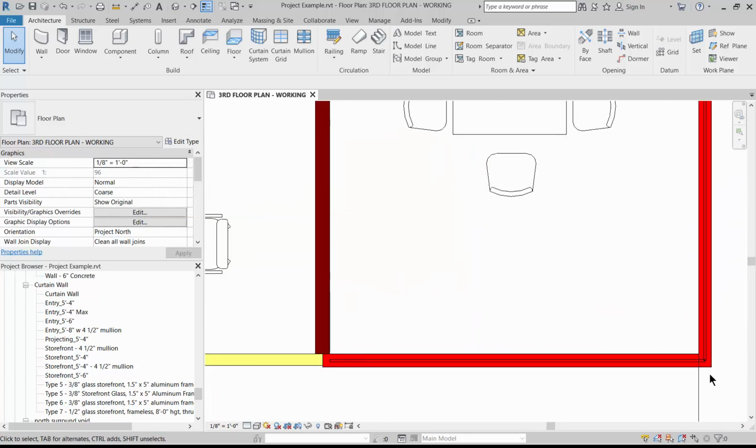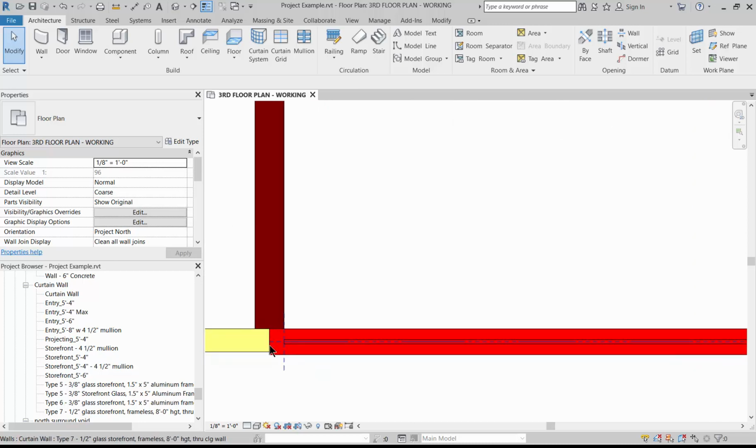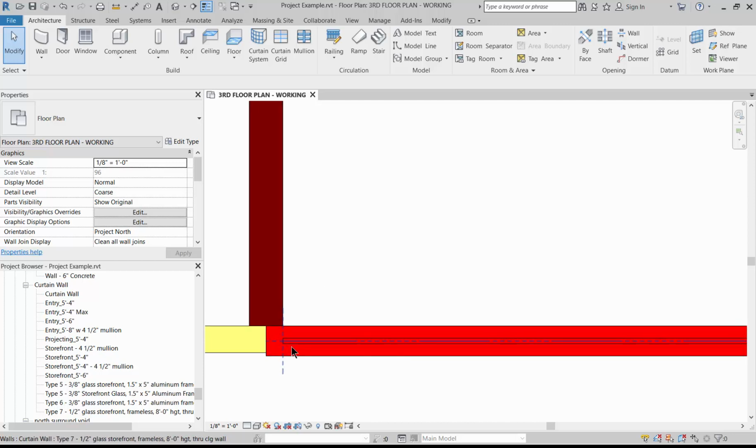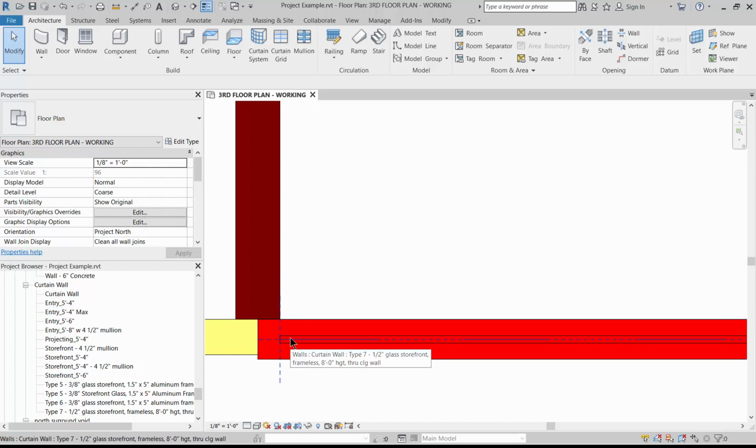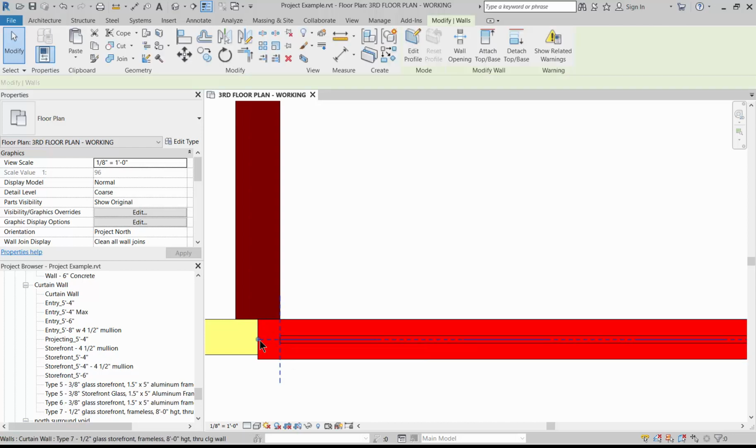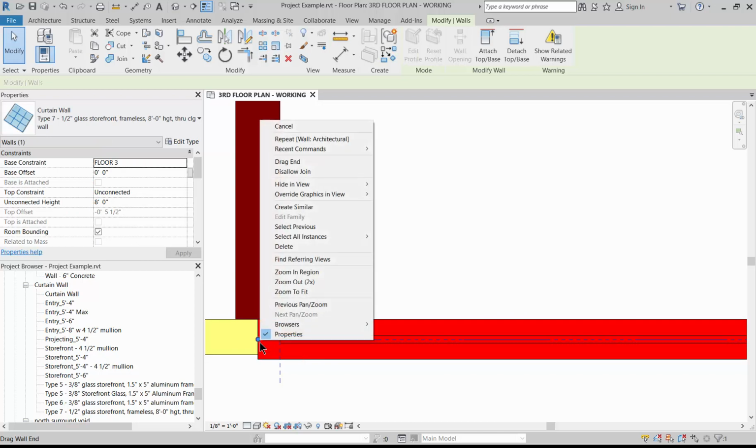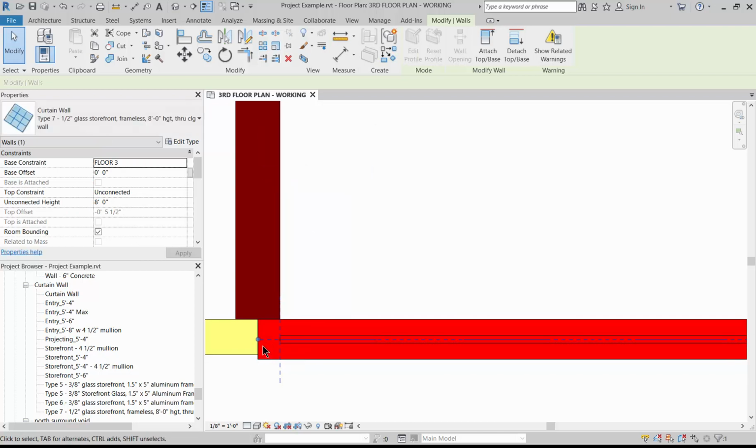So I'm going to put a door. I think I had the door on this side. Because now there is glass here, it might be better to put the door against a solid wall. But one of the two things I want to do, I either want to leave a little piece of glass and then put the door inset, or I want to move in the whole glass. Remember, you need 4 inches clearance to clear your doorknob and all of the door hardware, just in case you remember that from the code class. So I'm going to pull it in.